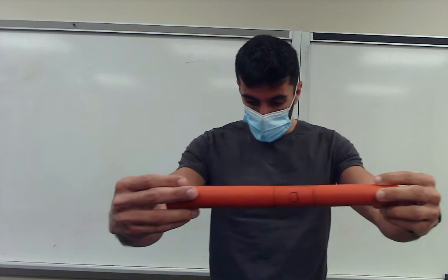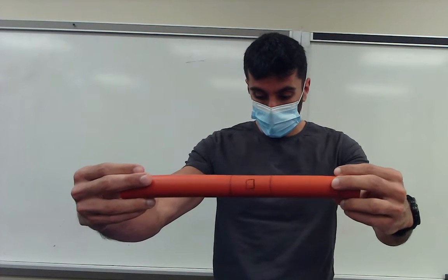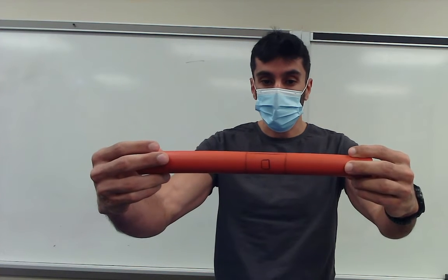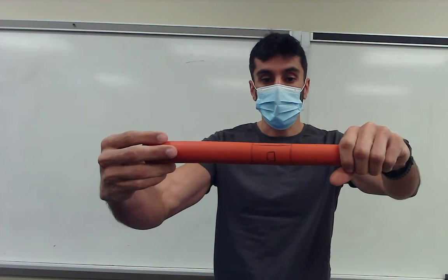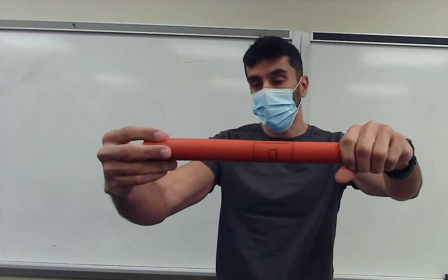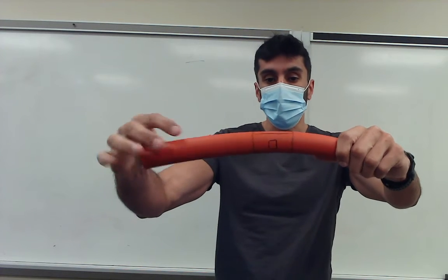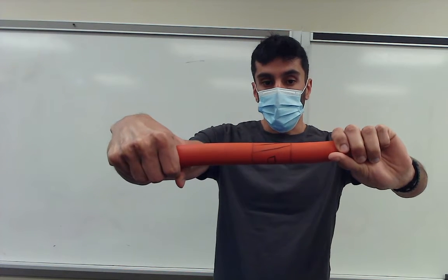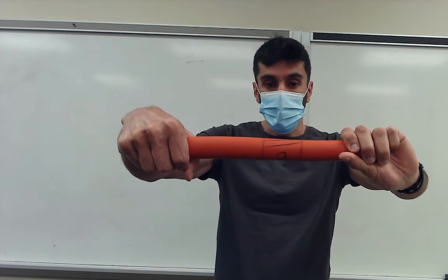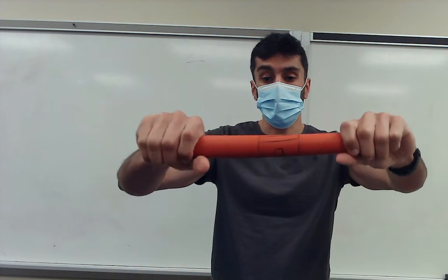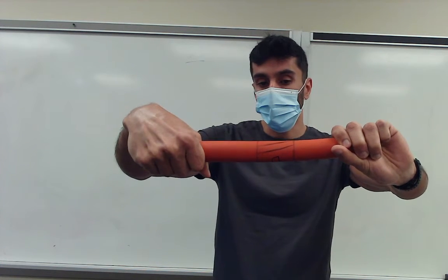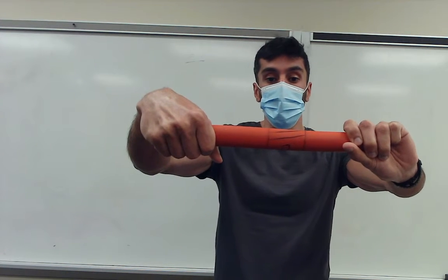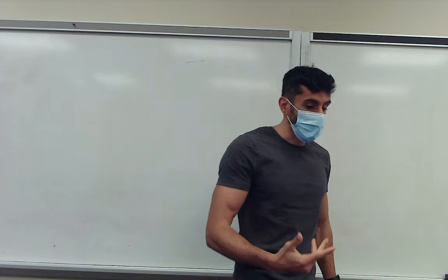So the idea is, if you see this rod, I basically drew, say, an element on it. Not the best drawing, but you can notice how the twisting happens and why certain lines remain parallel and others twist. Say the longitudinal lines, the ones in the length direction, will twist, but other ones, say in a parallel direction and the circumference directions, remain straight. And that was basically one of the assumptions that we use in our derivations.